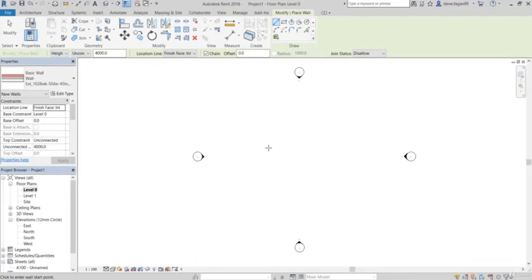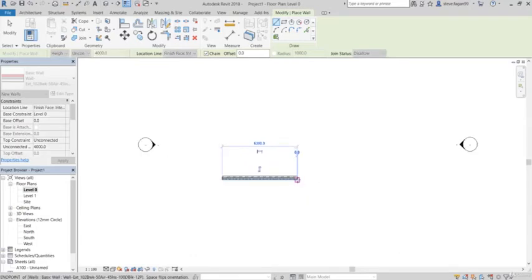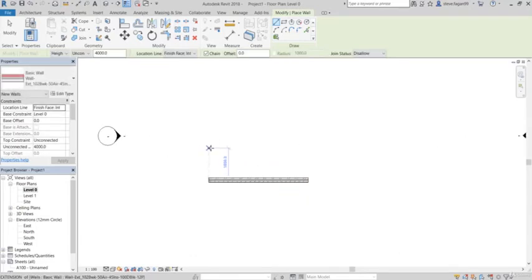When we're modeling a project, we are presented with multiple modeling aids. These aids will appear on almost all of the components which we will use. So if I draw my first wall and draw another wall above it, first thing we'll get is our temporary vertical dimension. So you'll see that there's a dashed blue line. That is telling me that that wall, when I start it, will be snapped directly above it.